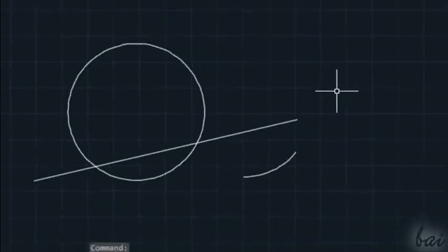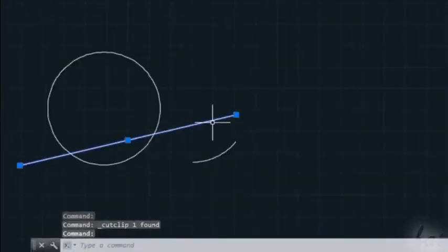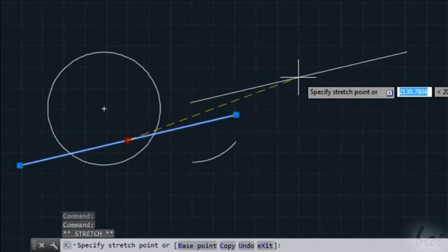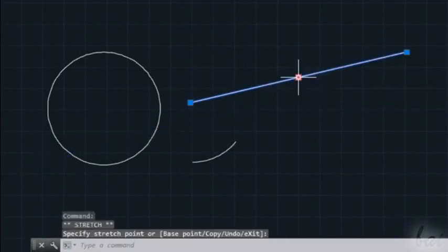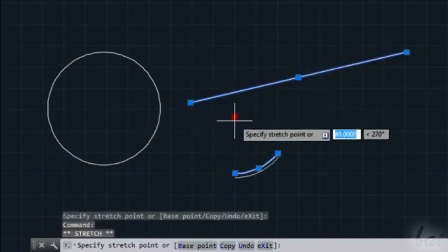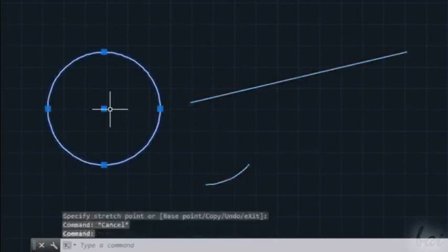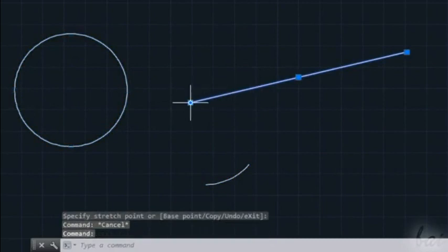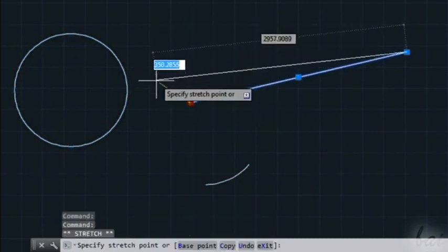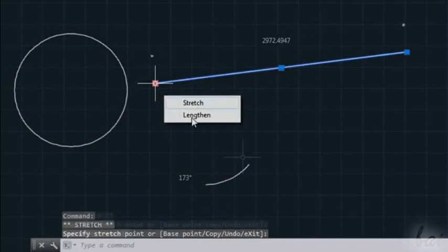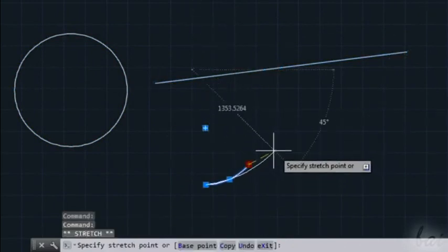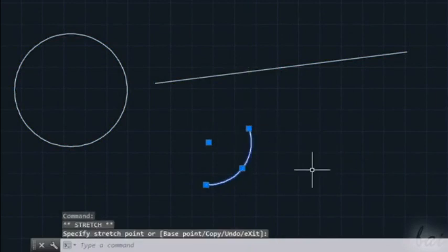You can move and edit objects fast while they are selected. When you select a line, a circle or an arc, you can click on the central point to move the object, without changing anything of its length. The other blue squared nodes are used to edit the object instead. Just click on them and watch the preview to adjust all properly.